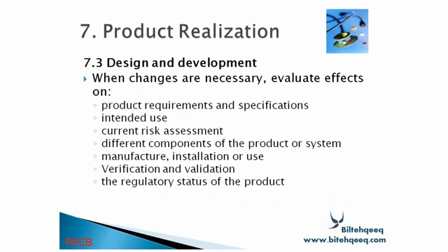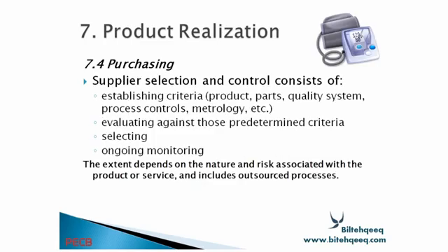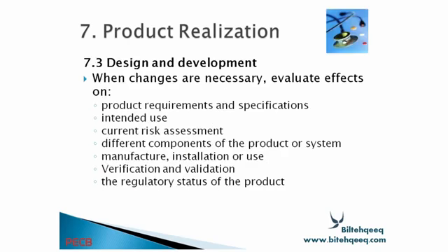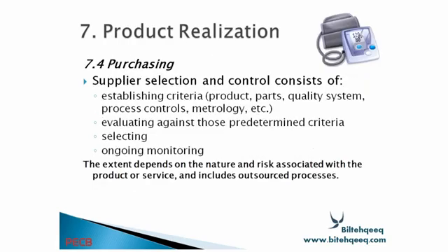You also have to study the effect of the change. If you change the design, you have to evaluate what effect it will have on product requirements and specification, intended use, current risk assessment, different components of the product or system, manufacture, installation or use, verification and validation, the regulatory status of the product. So if you are going to change the design, you have to see each and everything very thoroughly, what impact it has on the other activities.